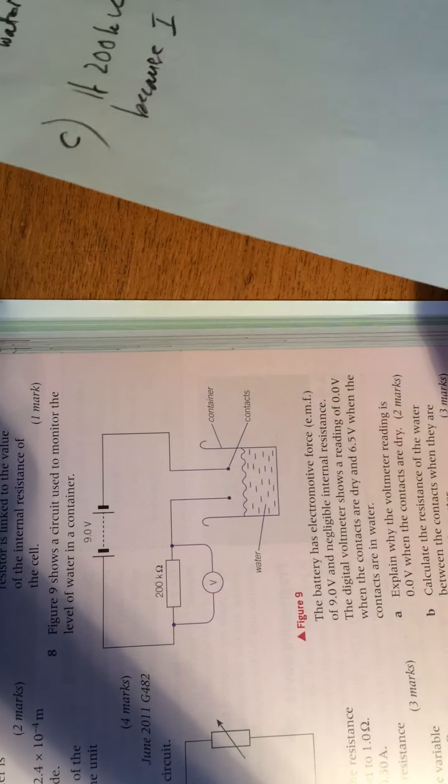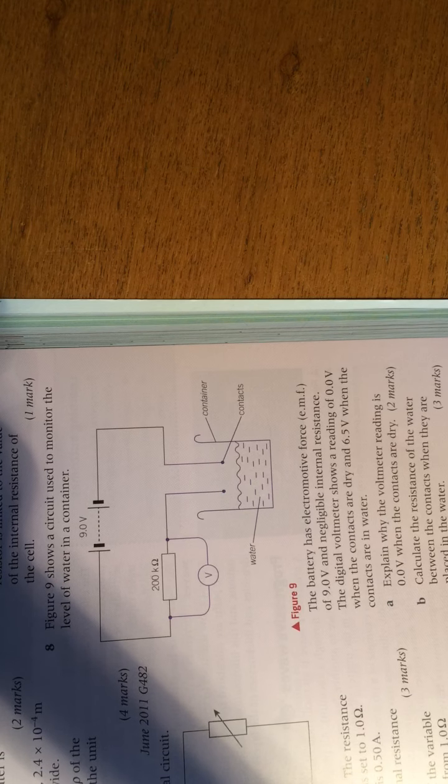It's important in amplifier and loudspeaker design, for example, where you normally get your loudspeakers at 8 ohms and you want the output resistance, or output impedance, of the amplifier to be about 8 ohms as well, so it delivers maximum power into an 8 ohm load.